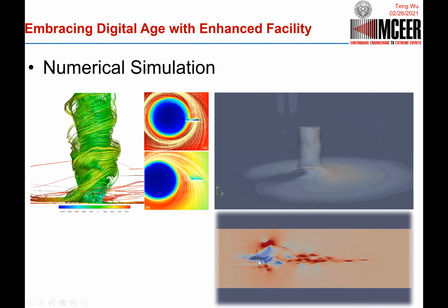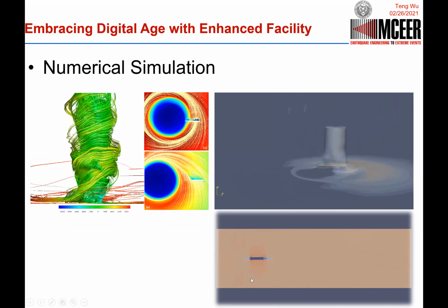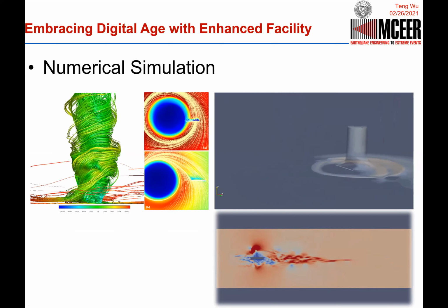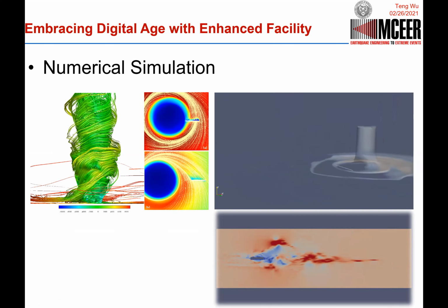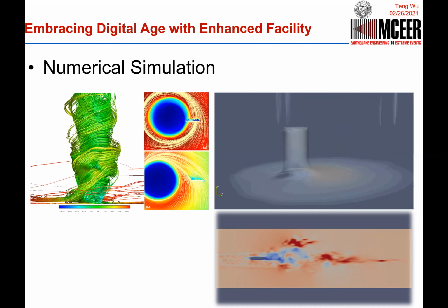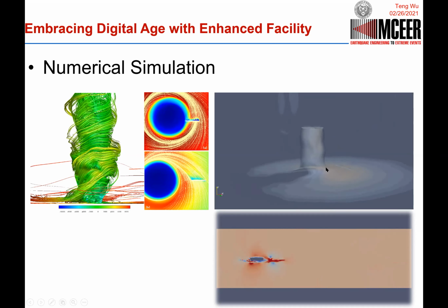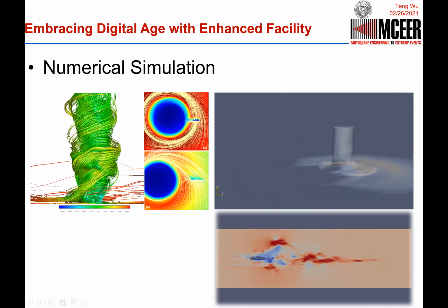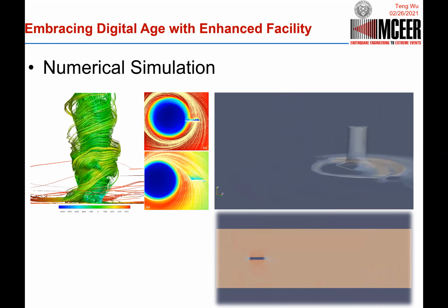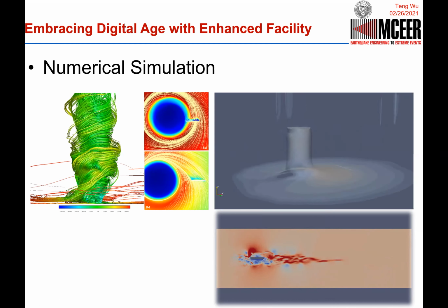Unfortunately, if the structure starts to move, that will modify the wind surrounding the structure, and of course then we'll have additional wind load. So if we put the structural response in this simulation, the computational demand will increase significantly further. It easily takes several weeks to simulate just one scenario, one case.